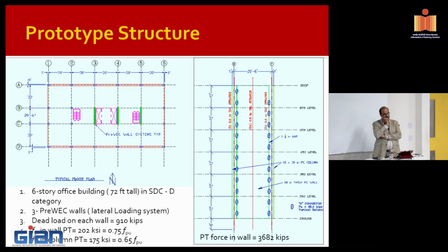I remember you were telling us that typically we target 30 to 35%, right? If I want more, then I can bring in some dual mass dampers and all that. You can add more connectors, you get more damping, right? But again, the 30% damping is not a requirement, right? No. What happened was, it was a back calculated value, back calculated based on tests people have done.